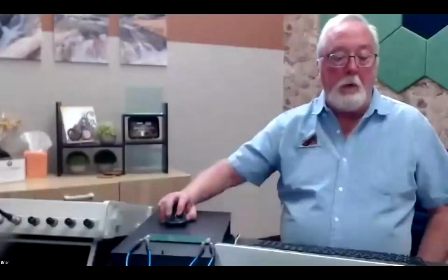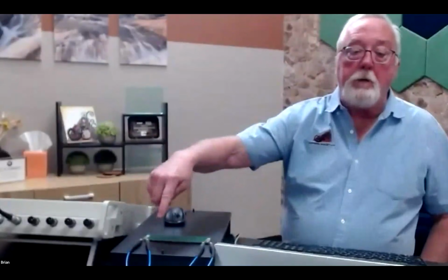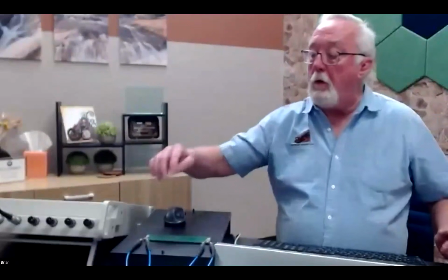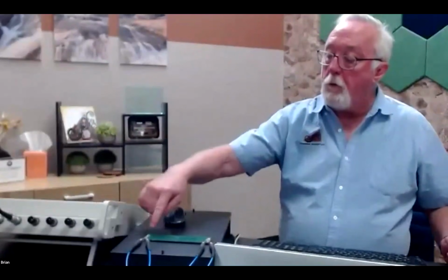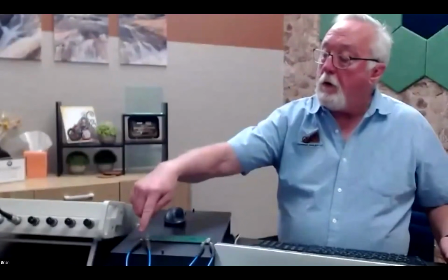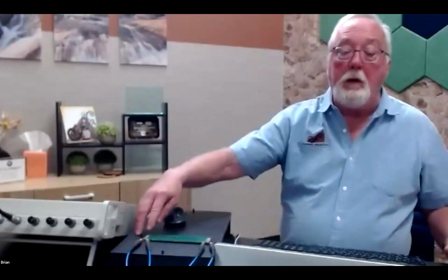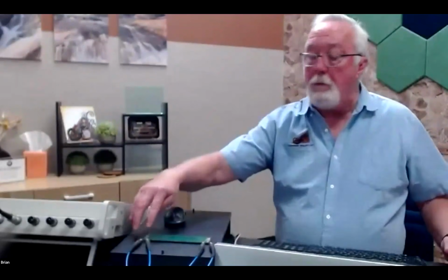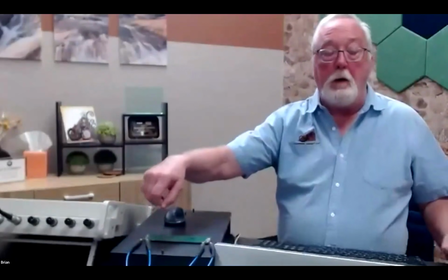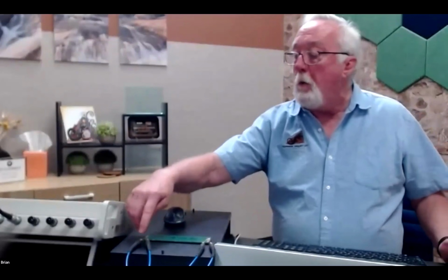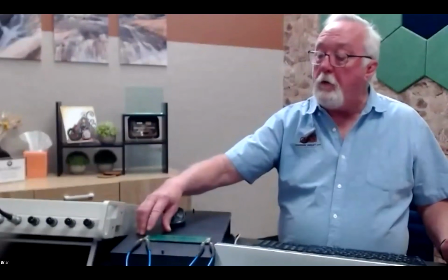Someone is asking if you can show the measurement setup. Is that possible? Yeah. The camera's not terribly close, but I have 2 traces on the circuit board up along the top here. I have these little SMA to open pigtails, and they're semi-rigid, and they're connected to the ends of the traces.